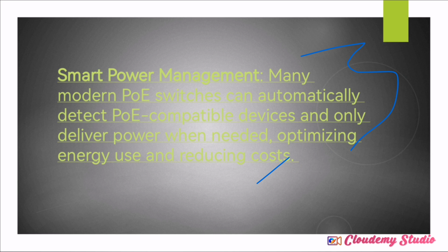So what is this paragraph trying to explain to us? What they're trying to explain here is, instead of you buying the chargers separately, the 9 volts or the 12 volts chargers, you just buy the PoE, and the same PoE is going to have the function where you can send the signals from the cameras to the NVR, and from the NVR to the monitor, as well as supplying enough power to switch on the cameras instead of using a separate power.